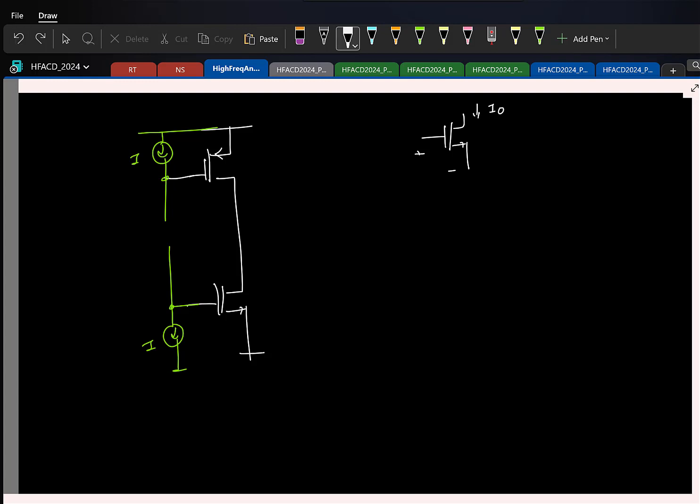So which means I'll basically put a MOSFET, let us say connect it to some Vx, we'll see how we can generate that voltage. Then this voltage will be Vx minus the required VGS at the particular current I. Okay. So this is fine with respect to the DC picture. Now, but the issue is, see here if I have a small signal V in, the gate voltage for the NMOS should be equal to that V in. That's what you want, right?